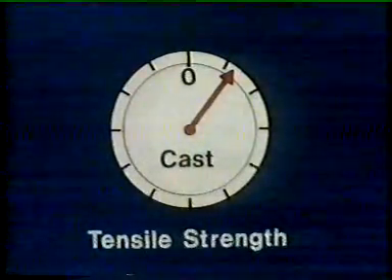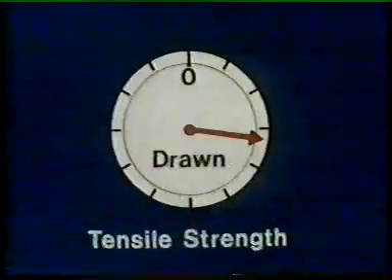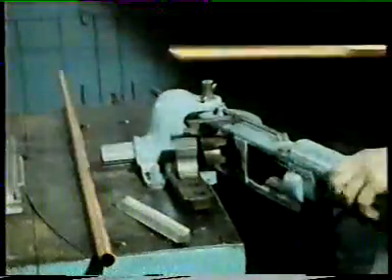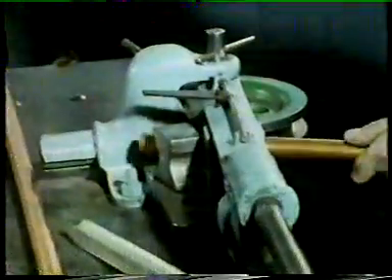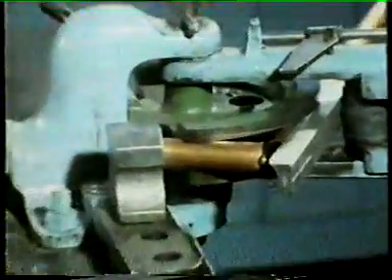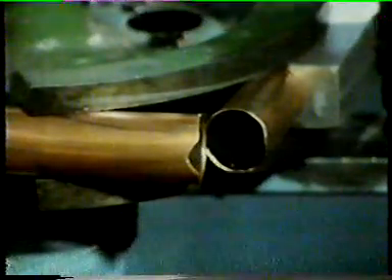So cold working has not only increased the hardness, it's also increased the tensile strength of the copper. It's brought about two useful changes in its mechanical properties. But what if we try bending a piece of cold work tube? Not all its properties are useful ones. Can you think what could be done to the copper to prevent this from happening?